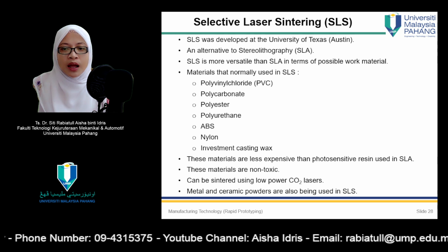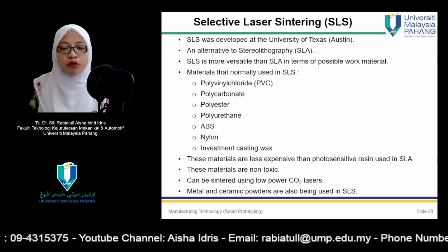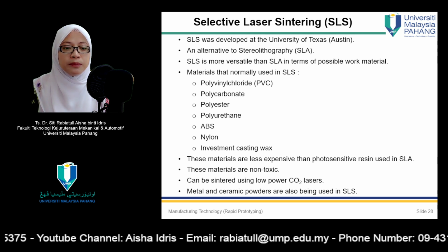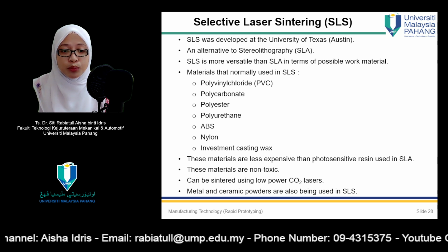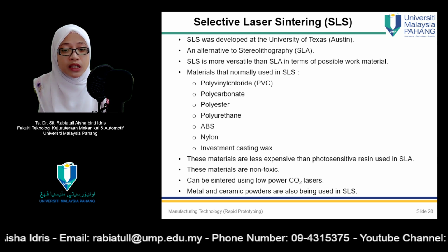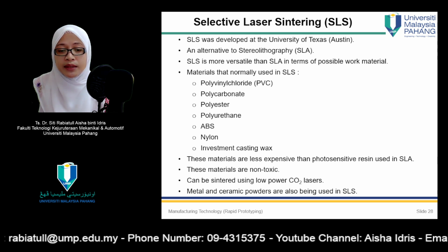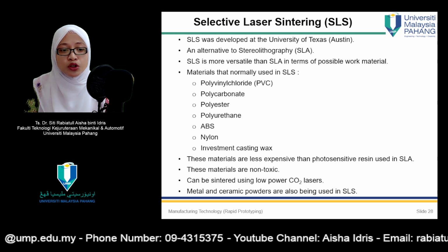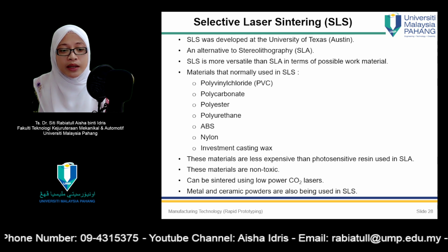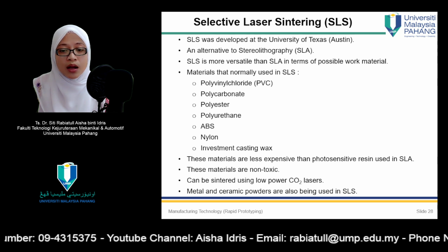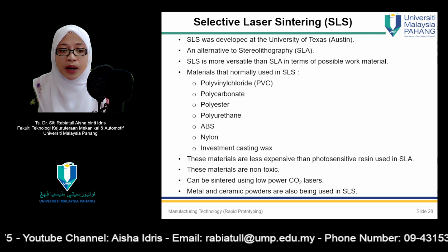So selective laser sintering, or SLS, uses a moving laser beam to sinter heat-fusible powders in areas corresponding to the CAD geometry model, one layer at a time, to build a solid part. After each layer is completed, a new layer of loose powder is spread across the surface using a counter-rotating roller. The powders are preheated to just below their melting point to facilitate bonding and reduce distortion. Layer by layer, these powders are gradually bonded into a solid mass that forms the 3D part geometry.